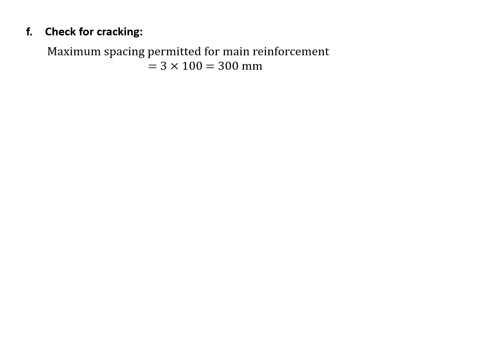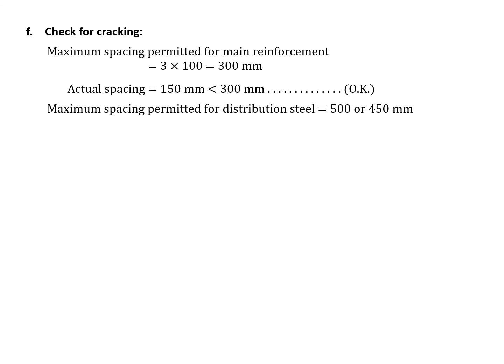Check for cracking, simple. Maximum spacing permitted is 3 into d, that is 300, but you have provided 150, so you are okay. And for distribution also suggest that you provide 150 and cracking is done.